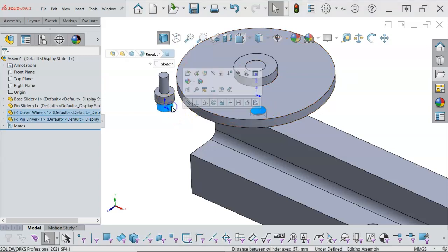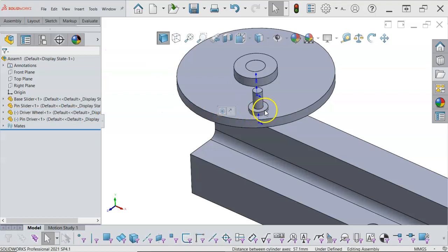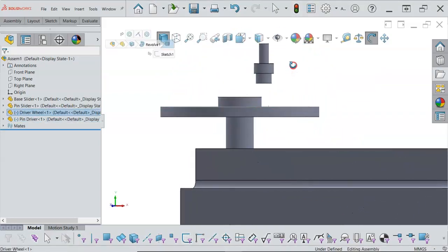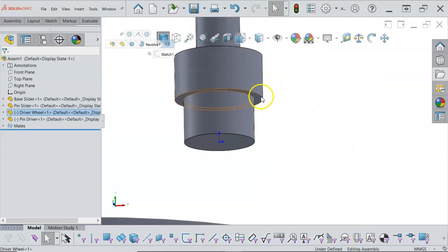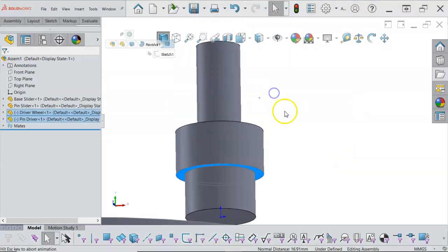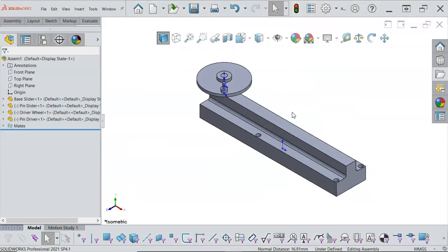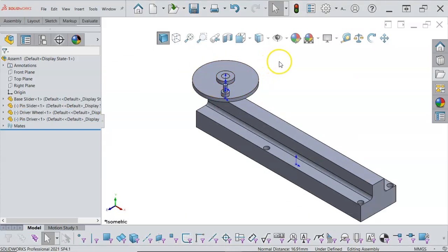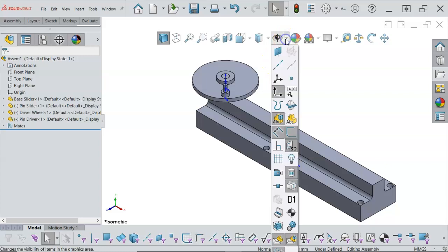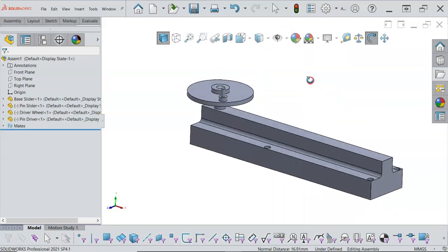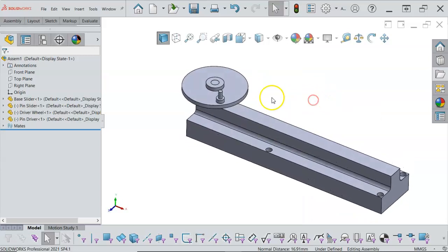Just kind of out of habit, I'm picking the cylinders first. So go concentric, need a little more room, separation, and all of those little origins are starting to add up and, well, visually starting to be a little annoying. So if I come up to the arrow next to the view, we turn the origins off, it just kind of cleans up the work area a little bit.